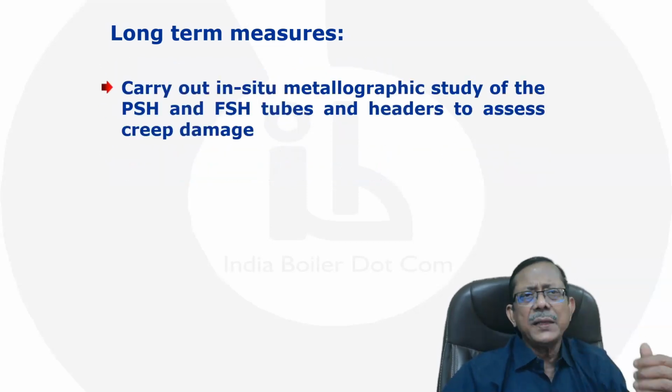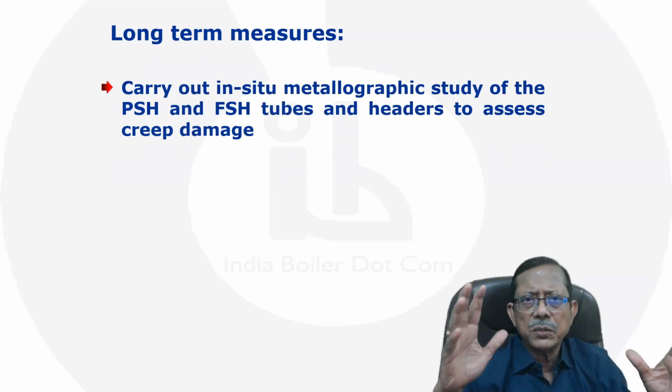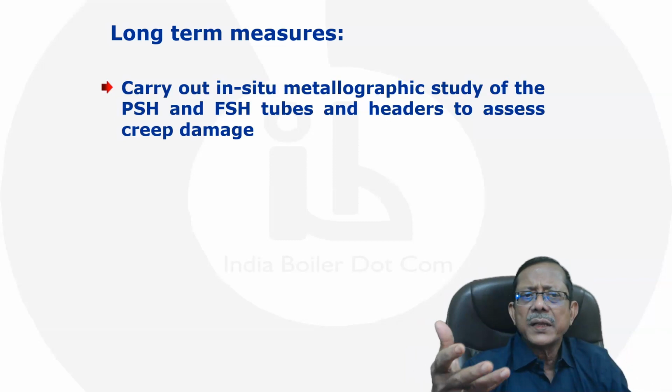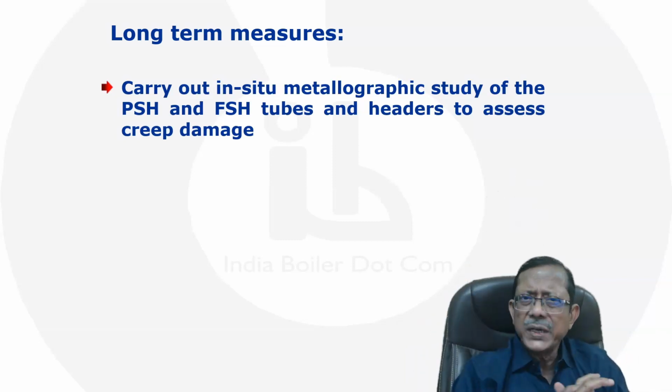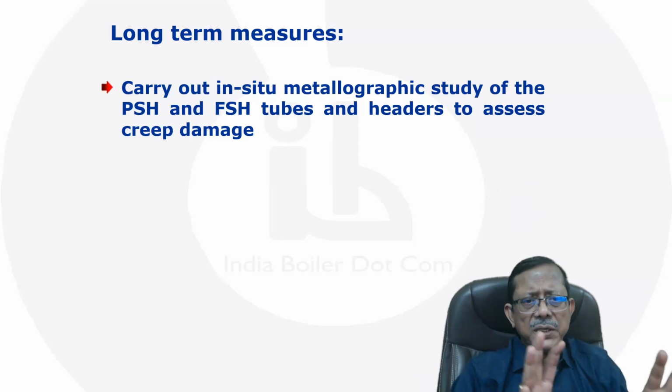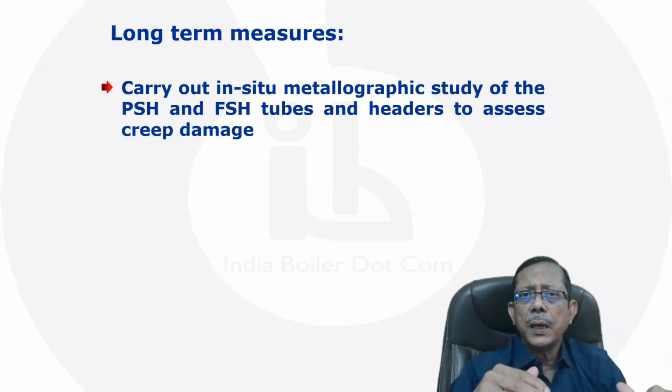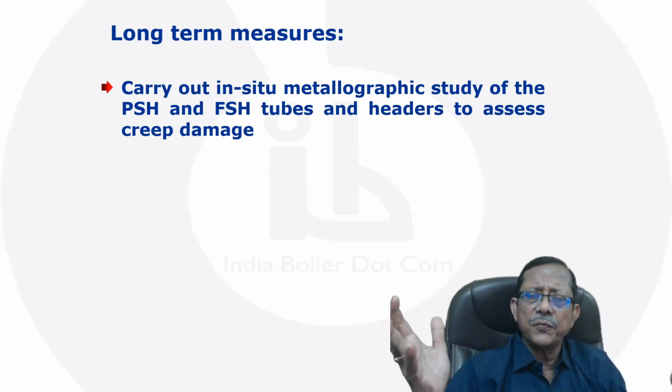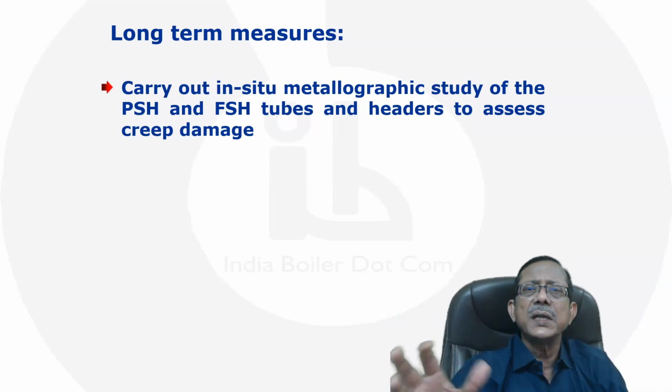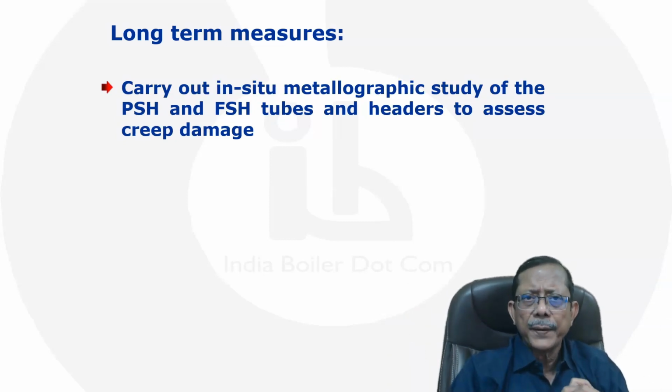And finally, as I shared, I have seen the indication of the superheaters getting affected, right? Of course, it has not yet failed, but that might also start failing in due course of time because of continuous overheating, right? So what is the creep condition? What is the creep health of it? To understand that, they have to conduct an in situ metallographic survey, right? So taking the replication of the components which are getting overheated, and to assess the creep damage, that is one thing.